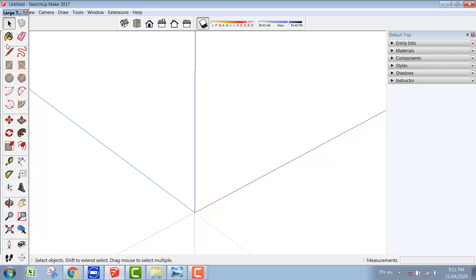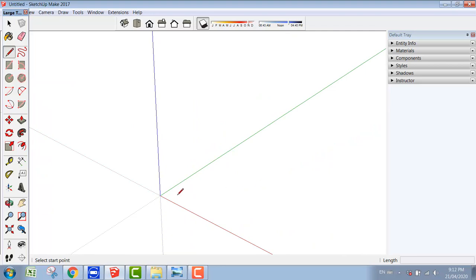I want to start from the second box here, and this is the drawing area. So let's start with the first one. The first one, the pencil, is the line. If I click on it, you just simply click and draw the line. Okay, if you want to have an exact dimension, before clicking here, I put the number. So if I want it to be 30, okay, just pay attention to the bottom right side.